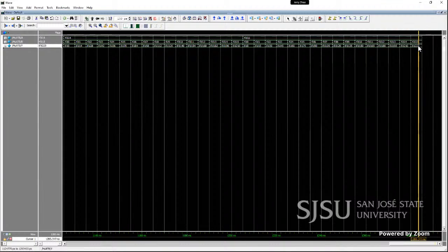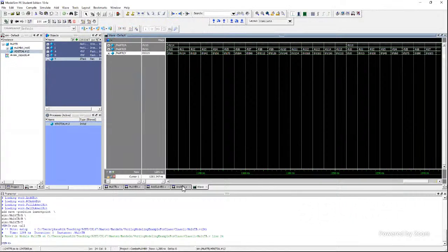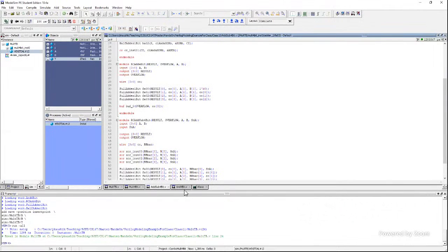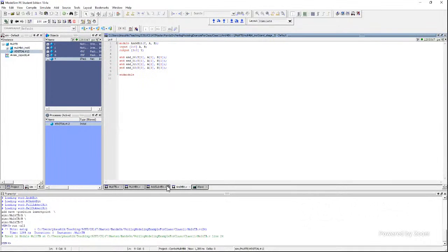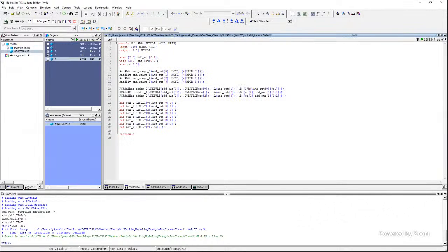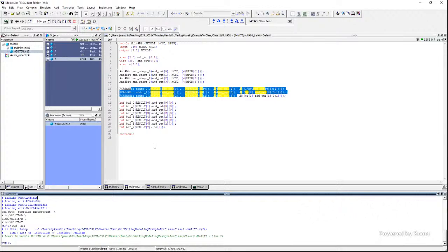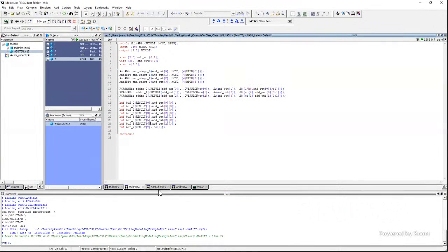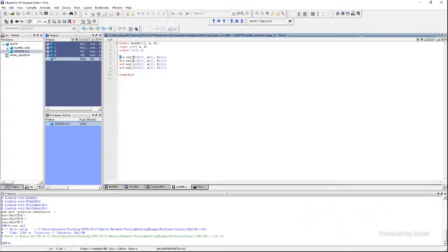That seems correct. So see that just by combining different combinational gates, here's my multiplier. We have used 4-bit ANDs and an adder, a simple adder. It is not an add-subtract circuit, it is a simple adder circuit. And if you drill down into each of them, your AND is simply a combination of 2-input single-bit ANDs.